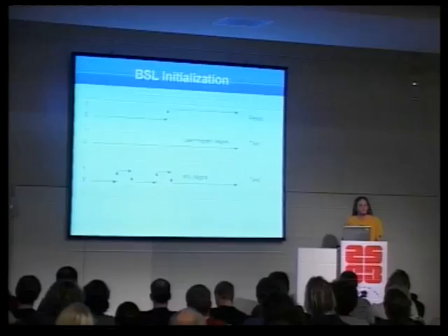So usually the chip will look at 0xFFFE, take those 16 bits and push them into the program counter. By doing it this way, it instead looks at 0x0C02. And then on different chips, you do different lines.